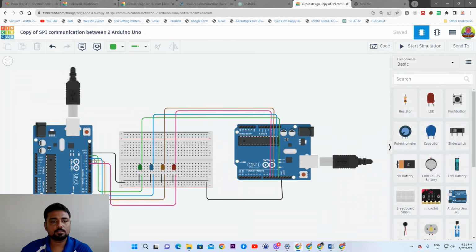One more thing you have to understand: you remember that the clock pin and data pin in the I2C protocol were A4 and A5 in Arduino. In the same way, in different microcontrollers it's always the same pin we have to use. It means for every microcontroller architecture, the serial clock and serial data pins are defined. For Arduino UNO it's A4 and A5. In different microcontrollers the numbers will be different. You have to identify which is the serial clock pin and which is the serial data pin.